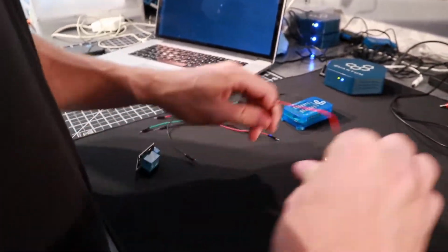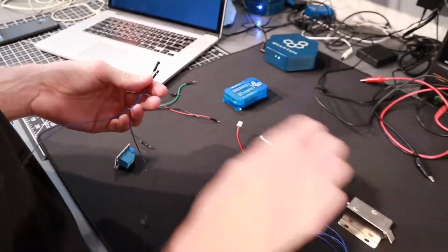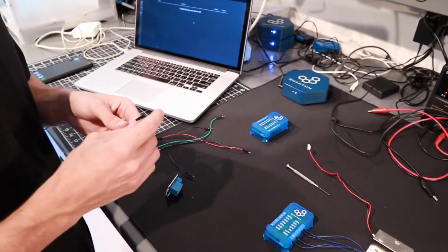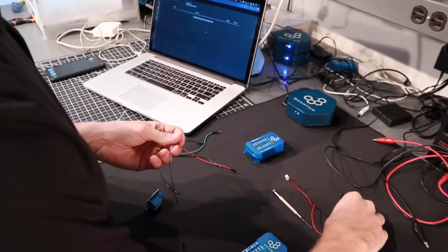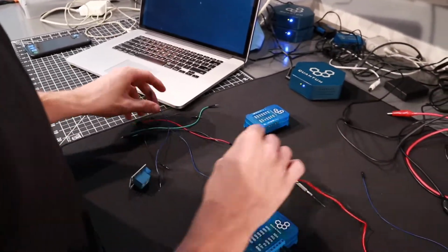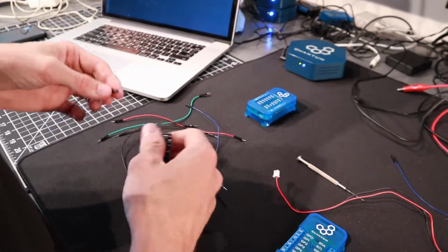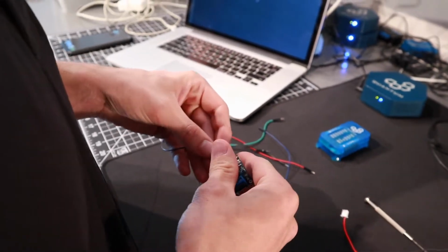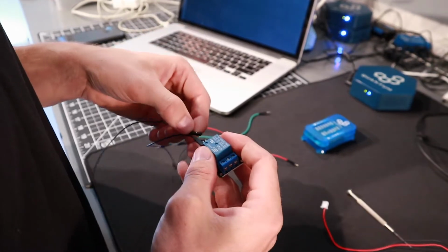How are you going to power this? We're going to power this for now through a power supply, but you could power it through multiple batteries, or you could figure out some other circuit to get the appropriate voltage. With this lock in particular, you can't power it through the client, just because it requires too high of a voltage. And that's why we use the relay, right? Yeah, we're using the relay to switch to a high voltage.